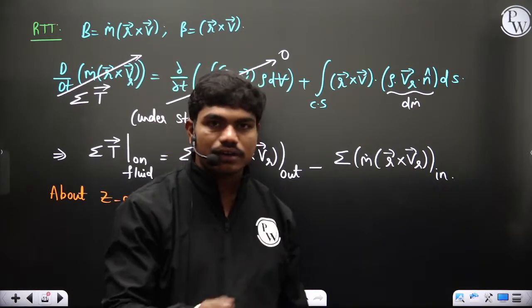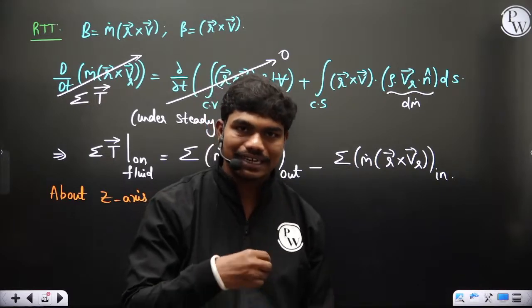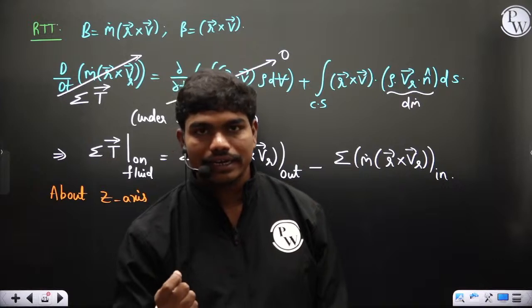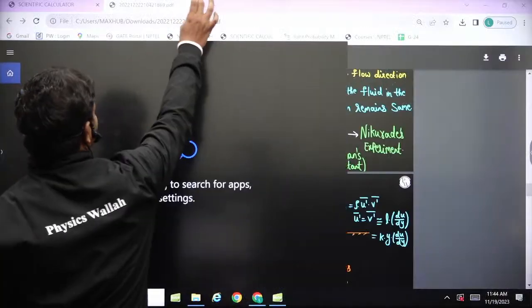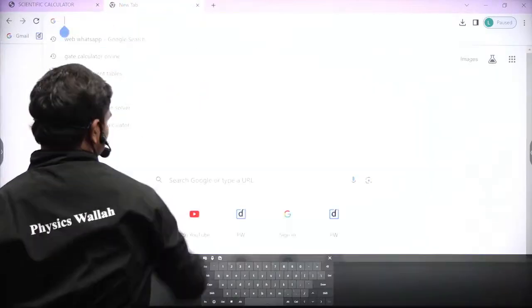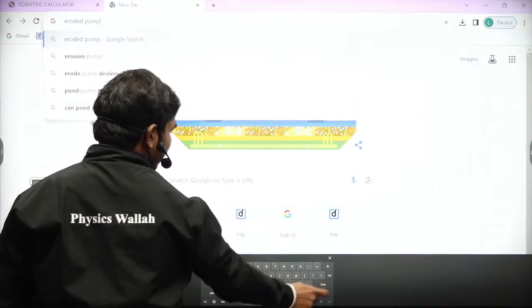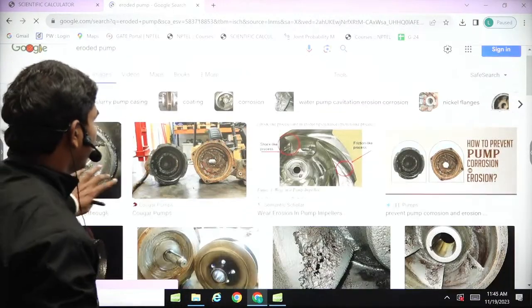Normally cavitation is one issue where the majority of the blades get damaged, and also erosion. Blade erosion is one major problem in industries. Normally if you see eroded pumps, since we are using this, let's take some advantage. You won't even imagine to what levels pumps get eroded. I have seen many in HPCL when I was working, but this is a good example.